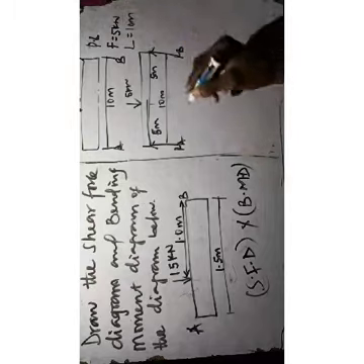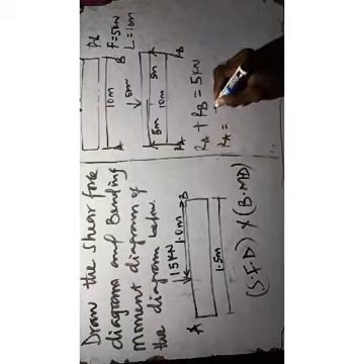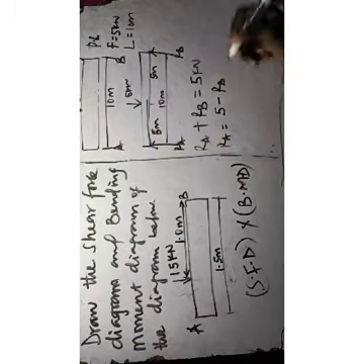Therefore I can now resolve the problem by saying, first thing, RA plus RB equals what? 5 kilonewton, that is the total force acting on it. This is first. Then you can make RA the subject of the formula, that would be RA equals 5 minus RB, equation 1. So the next thing is you take your moment. These are the reactions at point A and point B at both ends. Now you take moments.